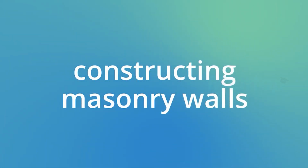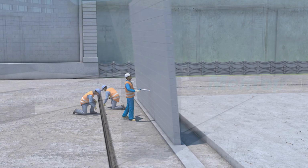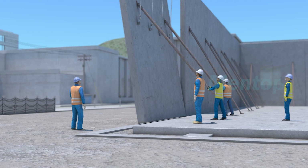Constructing masonry walls. Workers can be killed or seriously injured when building concrete or masonry walls. These walls are very heavy and are self-supported until they are braced or otherwise secured. If not careful, workers can be struck by materials when the lifting equipment is putting the slabs into position, or when materials are not shored properly and are not yet stable.